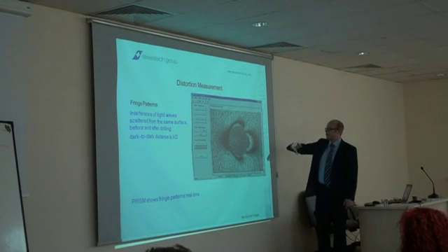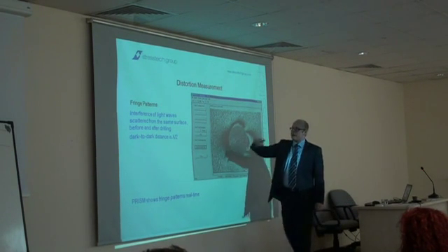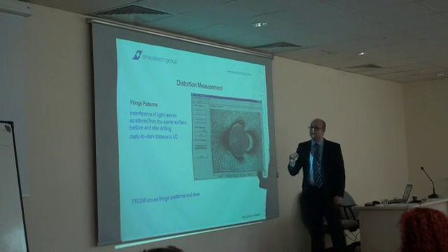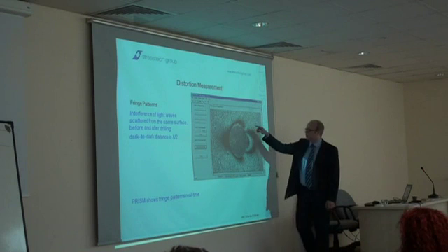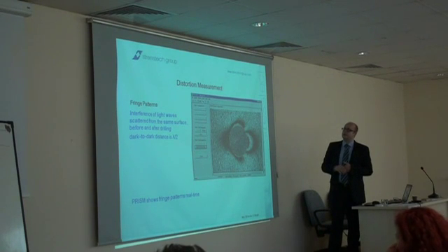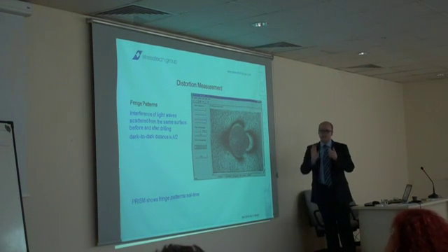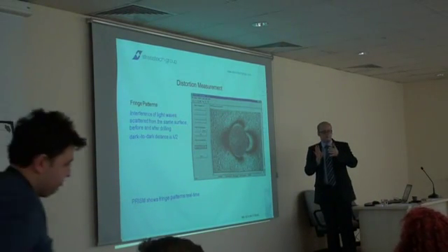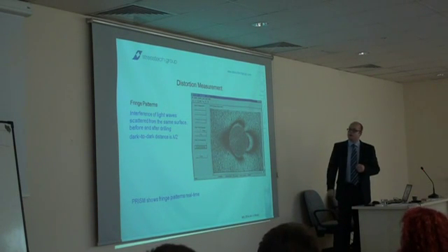And actually what you see when you make the measurements is this kind of fringes, the interference of light waves scattered from the same surface before and after drilling. So when you see this kind of image or video on our laptop, you know that you are releasing stresses, but you cannot say whether it is compressive or tensile stress. In this video we have a pre-image set and a live video, so that we can get to those fringes. So it's before and after drilling.